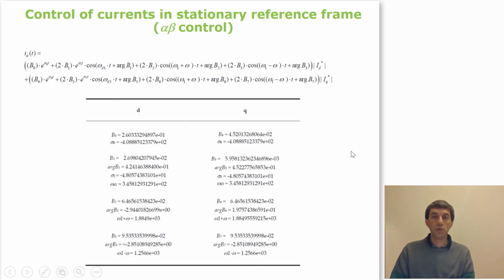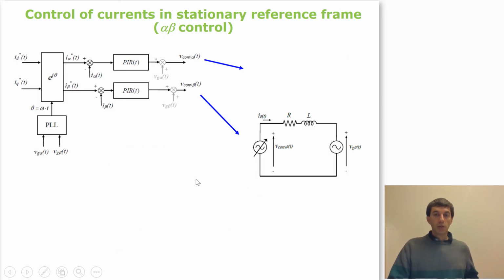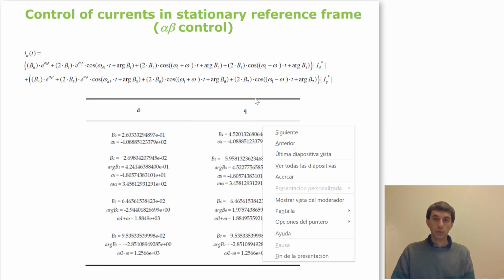So by using the residue function from MATLAB, we can obtain the numerical values for these gains. And here, I'm not going to show it, but in the book it is provided that, if we compare these analytically obtained expressions with the one given by, for instance, the blocks provided in Simulink, there is an exact match, so we can say that they are validated, they are true, they are good.